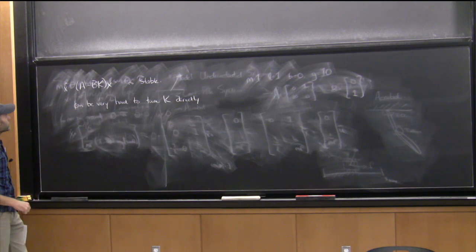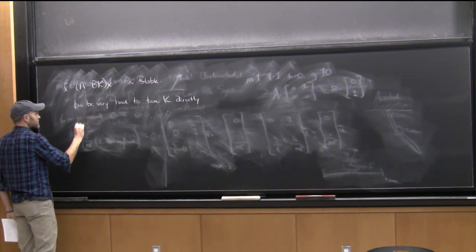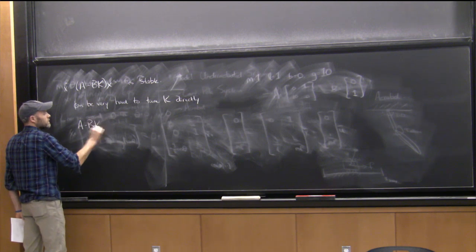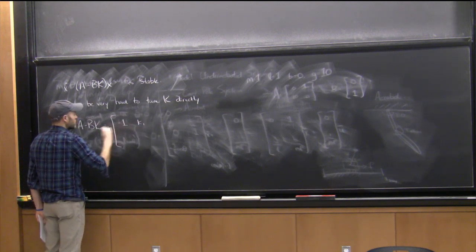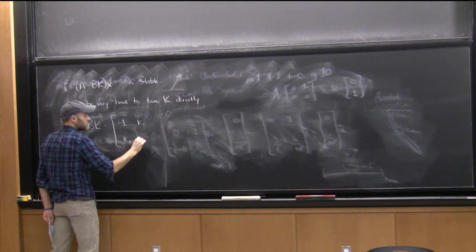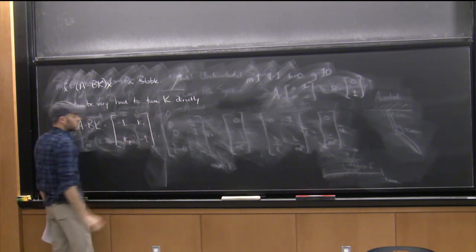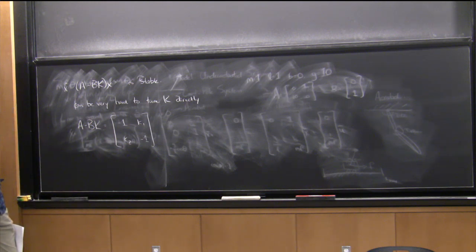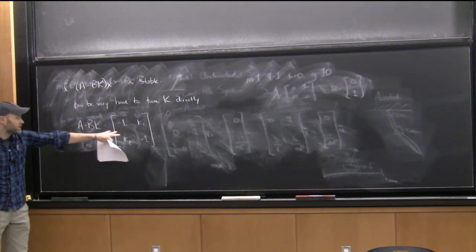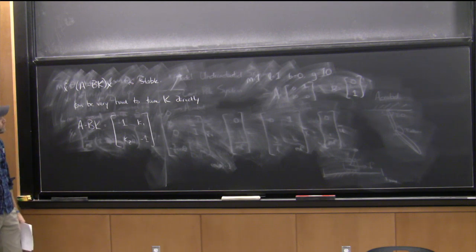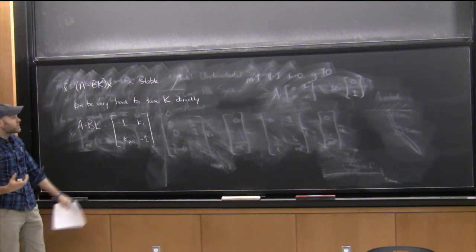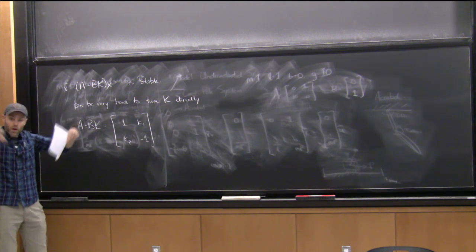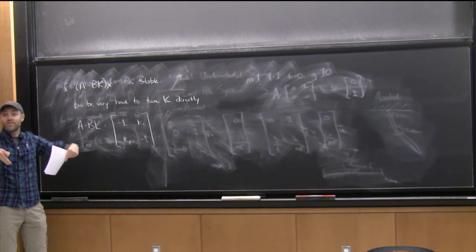Okay? So I can come up with a trivial example. If I make the following system, K1, if my closed loop system ends up being as simple as this, which could easily, simple choices of A and B would generate this, right? So how do I know that this thing's stable? I have to take its eigenvalues, and for a linear system, and you can see from the plot, you want all of the eigenvalues to be less than 0, right?